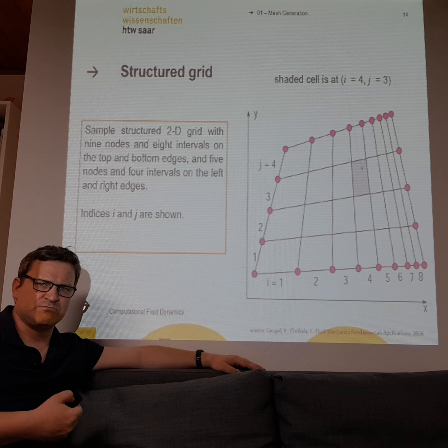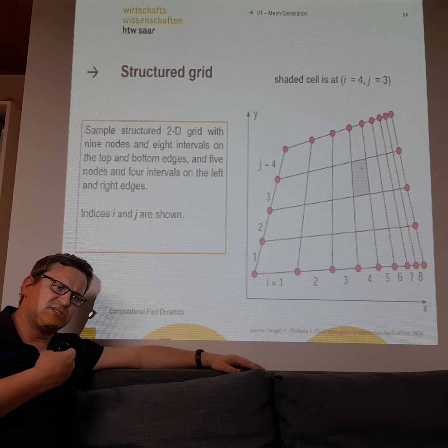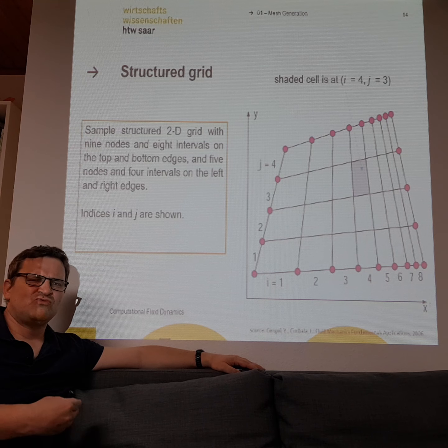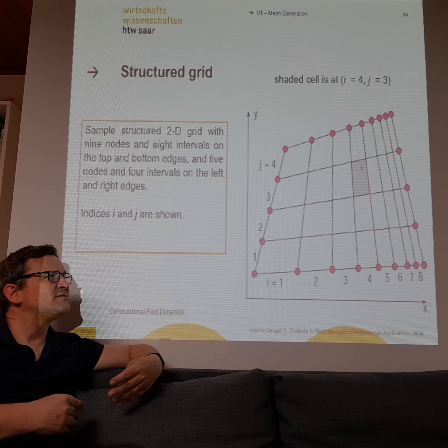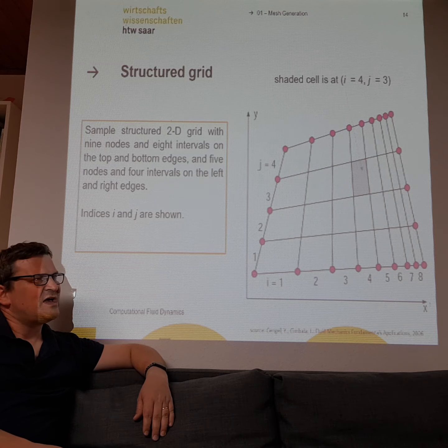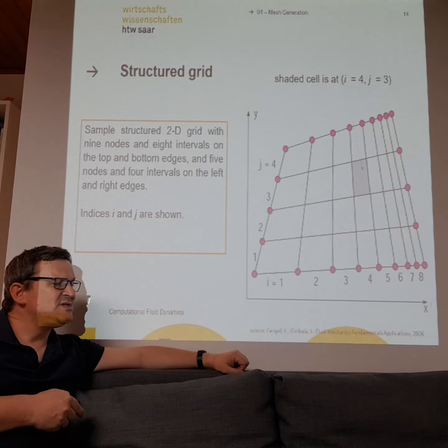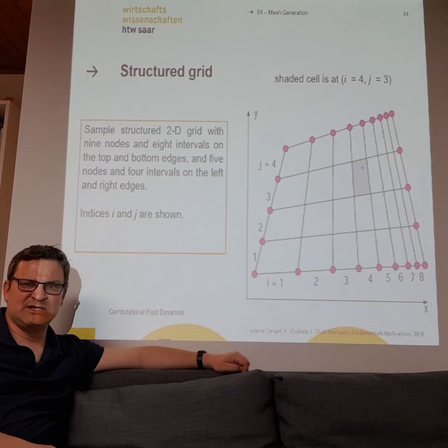That's a structured mesh. And CFD codes that run on structured meshes are really stable, mass conservative, momentum conservative. You won't have so many problems solving such a mesh, and it makes it much easier to solve numerically if you have angles near 90 degrees.